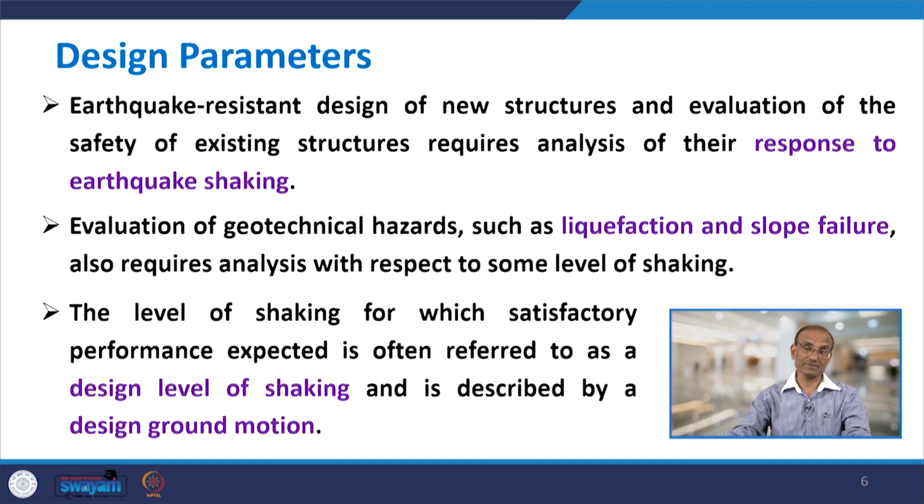So, how they respond when these structures are subjected to earthquake shaking, whether it is for the new structure or for the existing structure, is important. And evaluation of geotechnical hazards, for example, which include liquefaction and slope failure, will also require analysis with respect to some level of shaking.